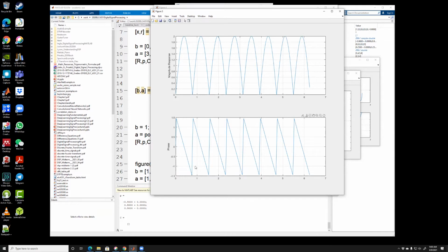When we look at the phase of this filter, this is a linear phase filter. When you do a wrap of 2 pi, that will give you a straight line for this phase. We really like a filter that has a linear phase because we know if it's a linear phase, that is just a pure delay. That's just a delay of any input you give me. This delay theoretically is the same for all frequency components in the original signal. I've not distinguished any of the frequencies. Along the line, it gives me the same delay. Now we have a linear phase. The reason is that this filter is really an FIR filter, finite impulse response.